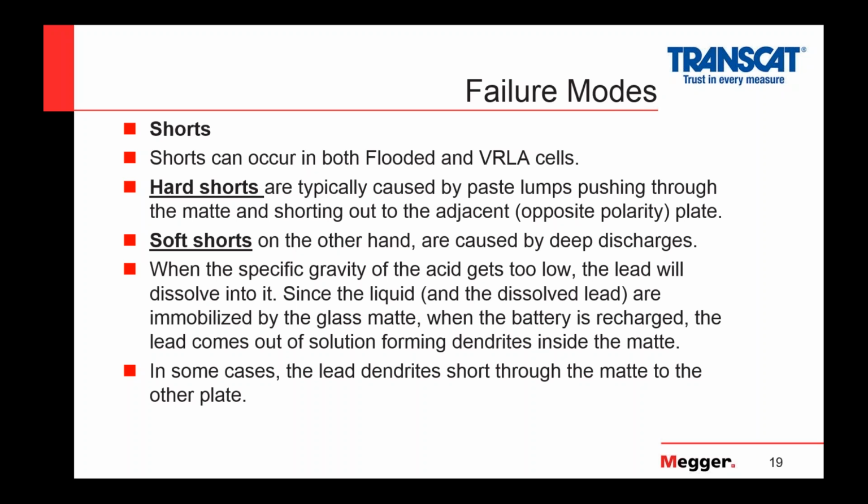When they get discharged past that 80 percentile, it's called watering the battery. The specific gravity of the electrolyte approaches that of water, and what ends up happening is the lead will begin to dissolve into the electrolyte. In VRLA batteries, these can get trapped in the separators.